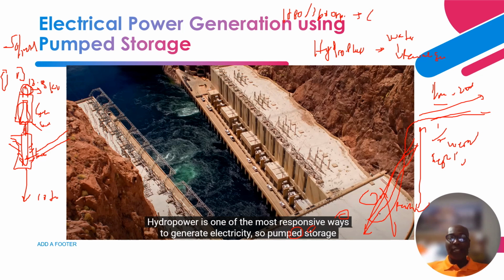That is for cylindrical synchronous generators, right? Comparably, salient pole hydro generators turn very slowly because of the number of poles, right? Cylindrical machines have 2 poles, and the speed in revolutions per minute is equal to 120 times f over the number of poles. Okay, so as you can see over here, a 2-pole machine leads to a faster speed, right?